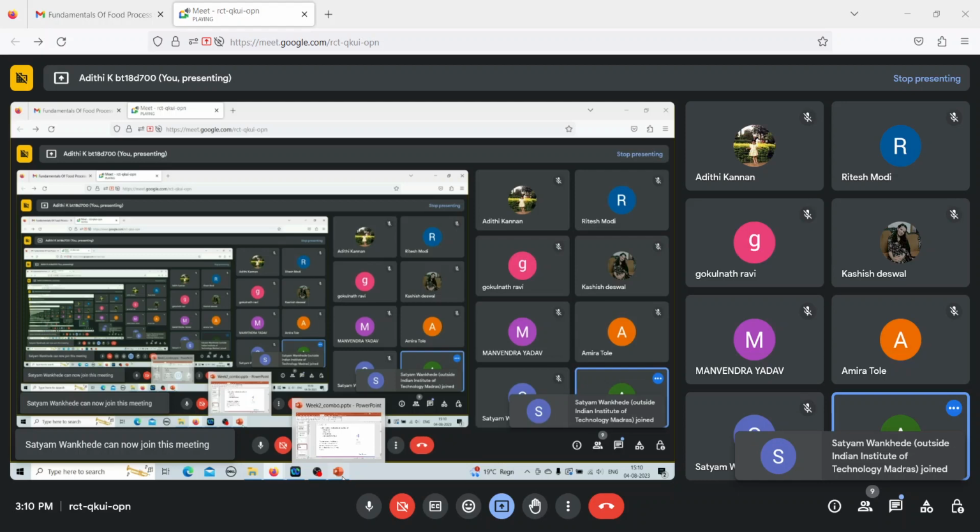So this is the concept of the Burger model. In the Burger model also, your strain will be equal to the summation of strains, because it is a combination of both the Kelvin and Maxwell models. So you'll have features of the Kelvin model coming in and features of the Maxwell model coming in. In the Maxwell model you had the stress the same and the strain a summation.